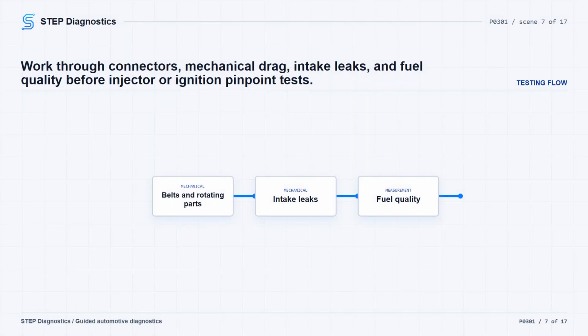With the ignition off, inspect the MDS solenoid connectors and related jumper connectors. Check connector seating, locks, corrosion, water intrusion, seals, bent or overheated terminals, push-back terminals, spread terminals, and terminal tension. Correct anything found and verify. If that checks out, inspect for mechanical conditions that can mimic or cause a misfire: belt slip, binding or misaligned driven accessories, crank sensor mounting or target wheel damage, an out-of-balance harmonic balancer, and severe tire or brake rotor imbalance.